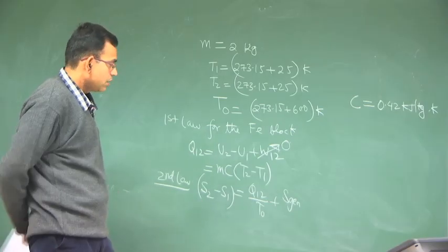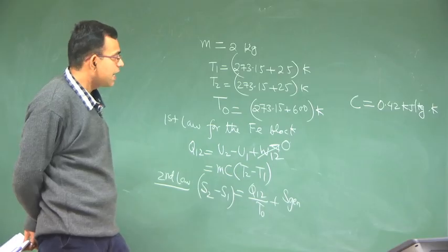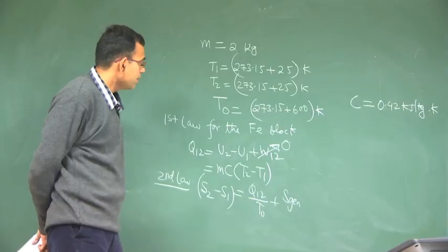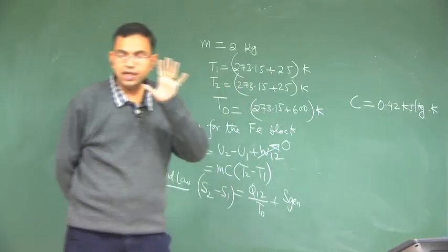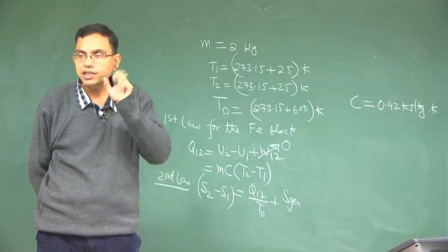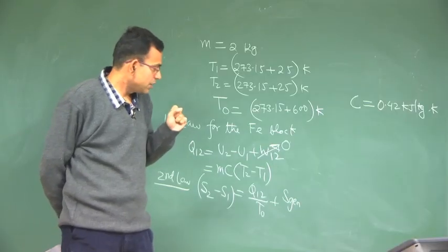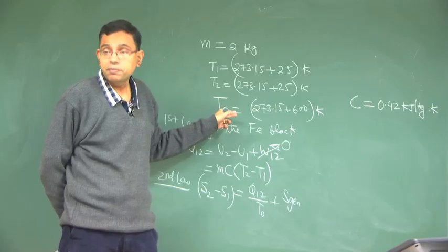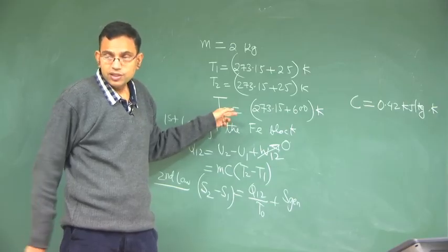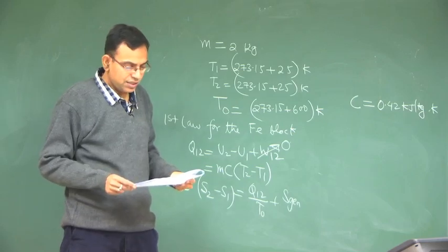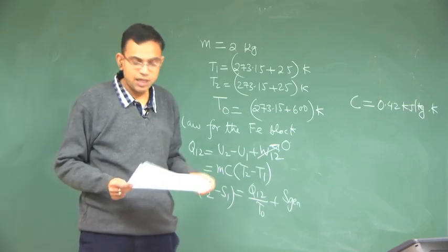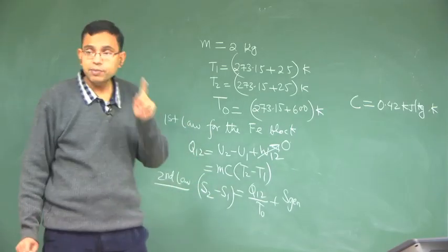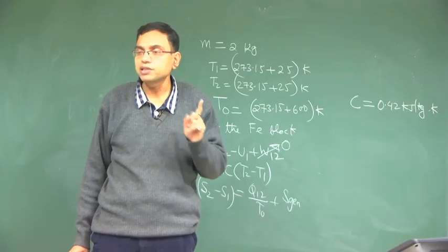Okay. So, in this case we have to clearly see, here we have to make a decision. What is the decision? The decision is, is this the ambient temperature or is this a heat source temperature different from the ambient temperature, right. So, here it appears that it is not ambient temperature, it is the heat source temperature at 600 degree centigrade. So, the irreversibility that you calculate, the reference temperature is always important.